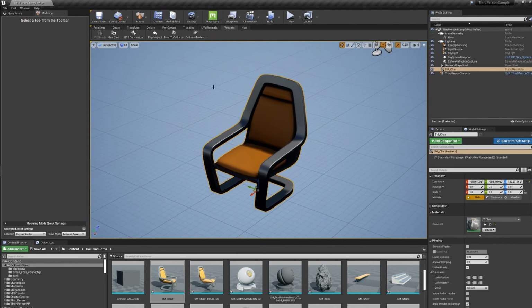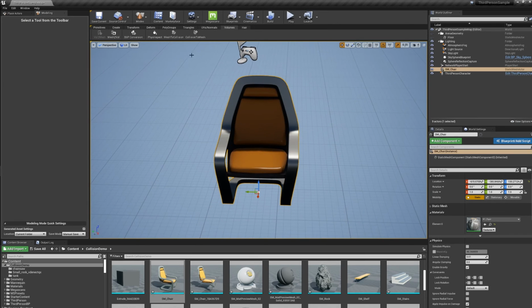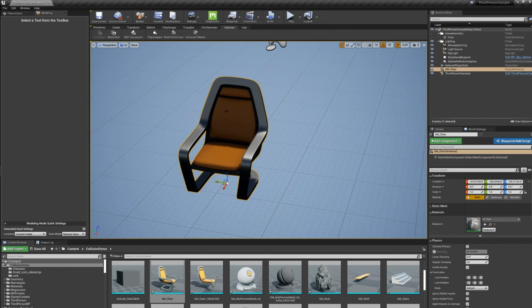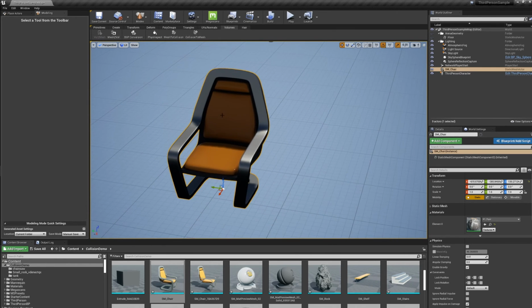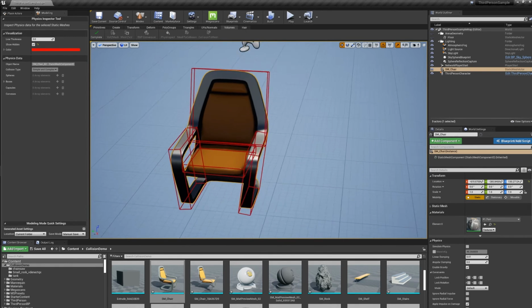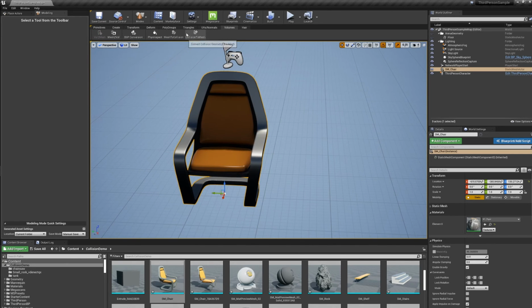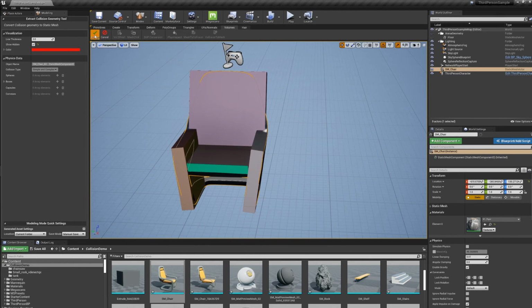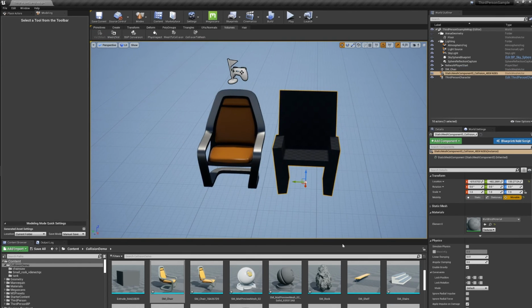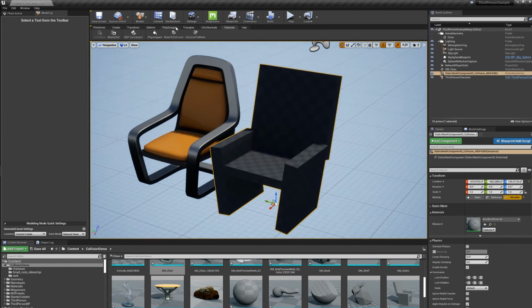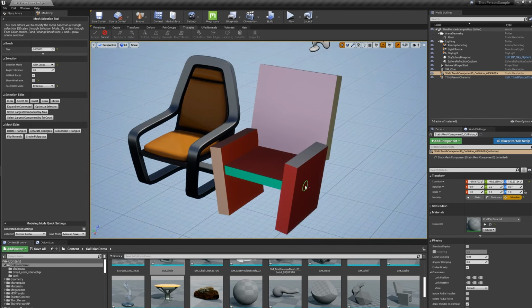Now, one small thing, right? The collision on it, if we use Phys Inspect, you see it's kind of coarse up here. So I'm just going to show you one more workflow that can be quite useful with that collision to mesh tool. These three boxes I think are fine, but I might want to use a convex for this piece back here. So one way to do that would be to use the collision to mesh tool. That's going to make a new version of it, right? These are actually assets too, so you can see here's the asset for this piece. Now what I'm going to quickly do is jump into the select tool and set this to all connected. I want to get rid of these three pieces.